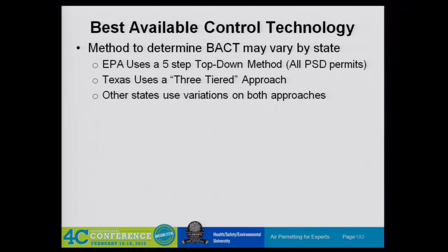Right, yeah, 0.06, and AP 42 is 0.1, and when we run it at 1800 degrees, we can't get 0.06. So I called the manufacturer, I'm like, can you make burners that... no, not at that. See, if it's not demonstrated, then again, the intent was to say low NOx burners was the technology, so whatever the best you can do with that technology should have been your BACT, right, instead of specifying a specific number for it.